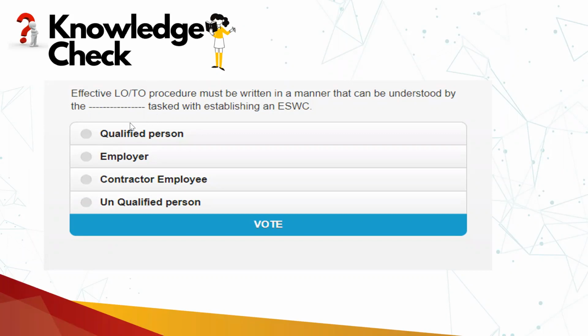Okay, so for this question, it sounds like it asks who is basically tasked with establishing an electrically safe work condition, so it goes with option A, qualified person. But generally, when we read the statement of NFPA 70E, the effective lockout and tagout procedure must be written in such a manner that it is understood by all the employees who are involved in establishing an electrically safe work condition. So this is the right